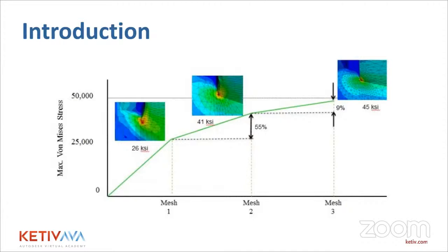You can control the mesh to lead to convergence by reducing the element size, and in conjunction, monitoring the changes in the results. Now, models with certain complex elements tend to converge with smaller element count than others, but the time and resources associated with these complex problems may sometimes be prohibitive. So most FEA studies, at the end of the day, require you, the analyst, to strike a fine balance between analysis time, the cost to run the analysis, and the desired accuracy.